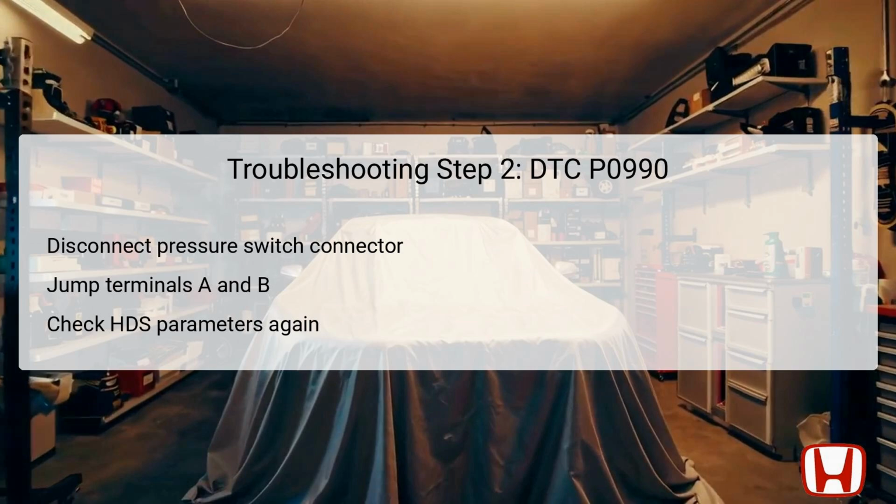After setting up the jumper, turn the vehicle back to the on mode, and again, monitor the parameters through the HDS. If the current conditions reflect that the 6th pressure switch is on and matches the threshold, this would indicate that the switch is faulty and should be replaced. If the readings are not as expected, further investigation into the wiring or other potential faults should be conducted.